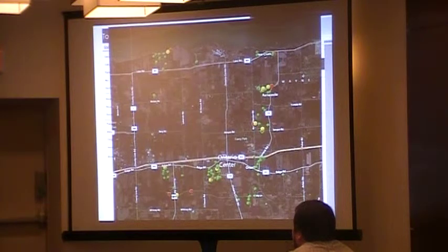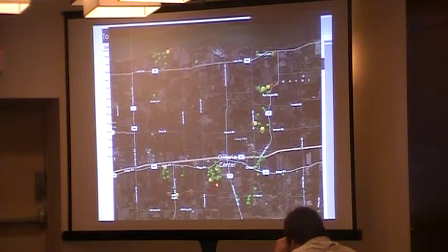And back to the initial problem of getting useful information out of that stack of paper, one of the things we're able to do now is because we also collected condition information about each one of those points, once everything was all said and done, we were able to go through and query that information and provide a web map back to the client. And there's all those little red dots are all outfalls that had poor structural conditions. Now they have something that they can go back out and use as a tool to go back out and fix things that are broken.